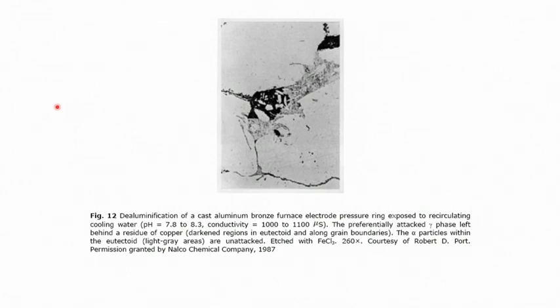it is very important that you find out the grain boundary microstructure prior to its application in an actual environment. If the grain boundary possesses any elements which are highly active or highly noble, particularly highly active, then the dissolution rate along the grain boundaries will be higher. But on the other hand, if it is highly noble in nature, like in the case of 304 stainless steel after arc welding operation, we get precipitates of chromium carbide along grain boundaries. So, this is highly noble in nature, cathodic as compared to the surrounding boundary regions.